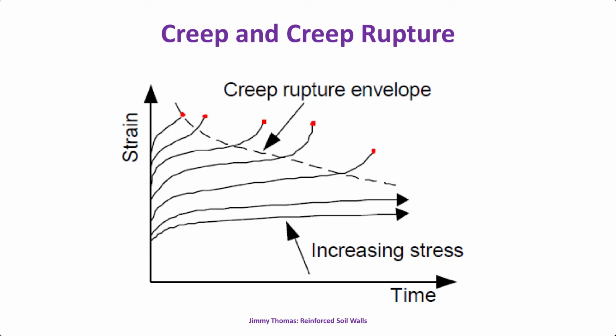as the load increases. That means as a proportion of the ultimate tensile strength. If the applied load is only say 10 or 20% of the ultimate tensile strength, the creep will be less. As I keep on increasing the load, the creep will be more.